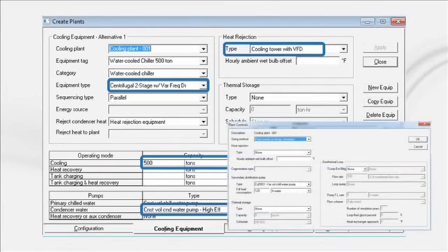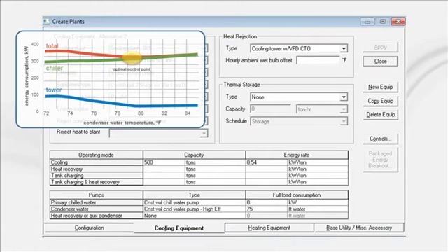You'll note that the dedicated chilled water pump's kW is set to 0 since the manifolded variable primary flow pump is in the system section. Once the base system is set, we can define our alternatives. The first is going to be chiller tower optimization.